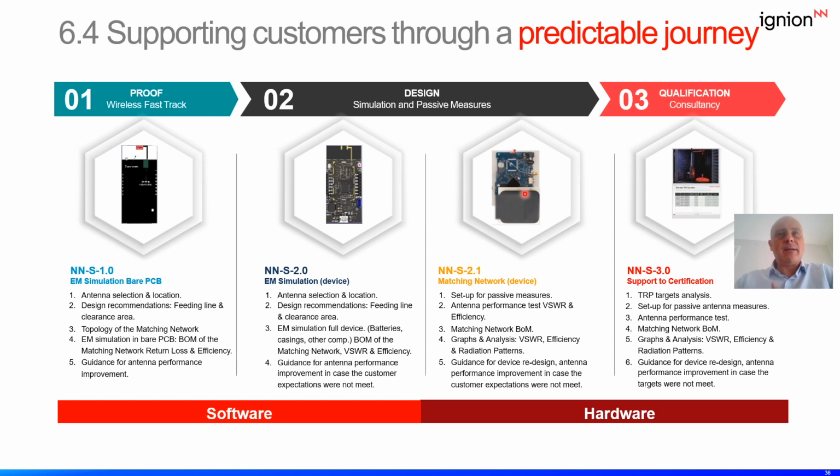Once you have the real PCB, the real device, we can also assist you in designing and implementing the matching network into your real physical device, considering not only the PCB, but the PCB fully populated with the battery and also including the casing. So with that, you get the matching network that best operates in your device.